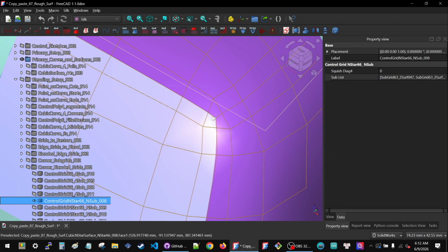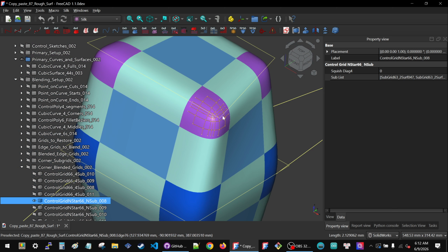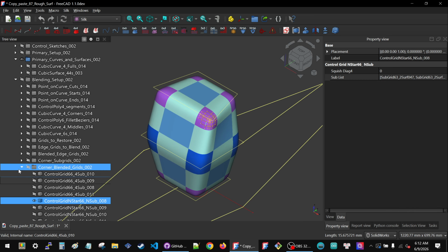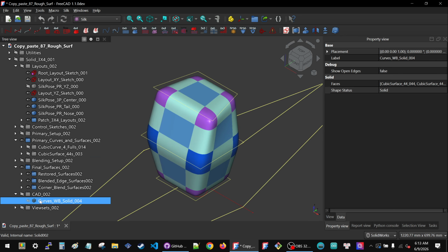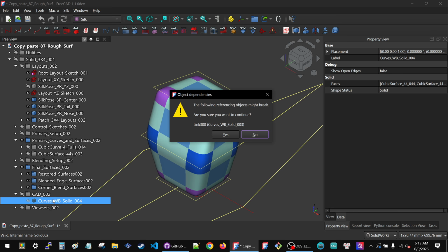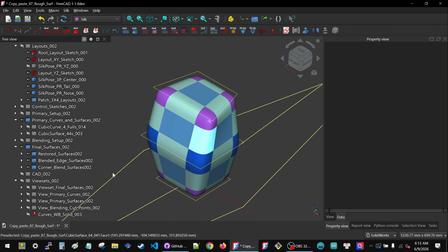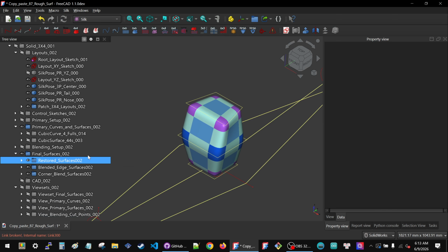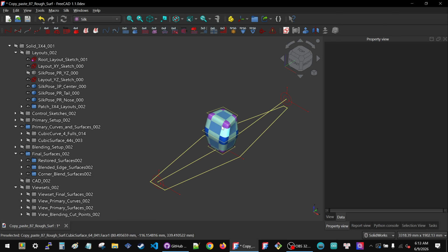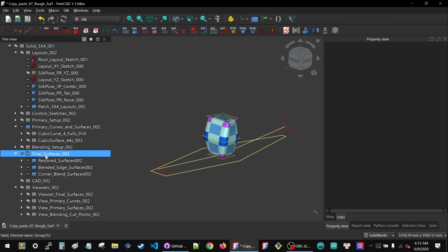So I will have to fix Silk if I want to keep recommending that people use this object even just as a preview. So what I'm going to do right now, and you're going to be seeing it along with me, is delete the solid, and I'll just remake it later. I'm going to delete this solid because I believe that it is what is crashing and causing FreeCAD to hang. So that's a heads up.